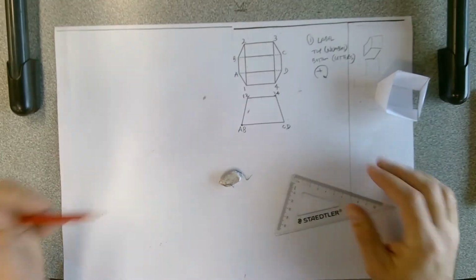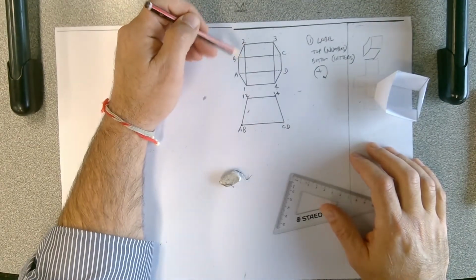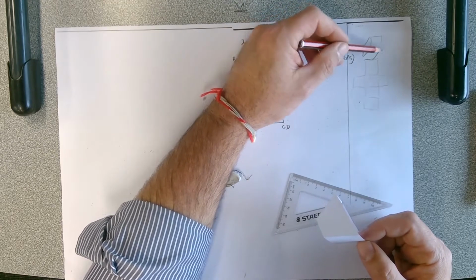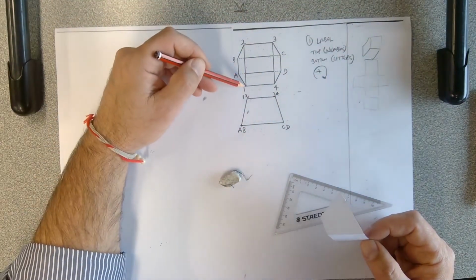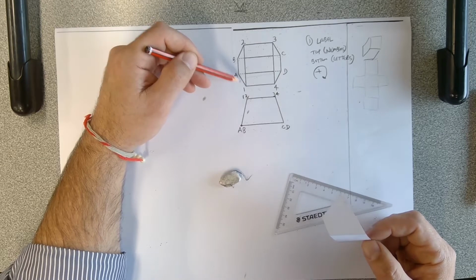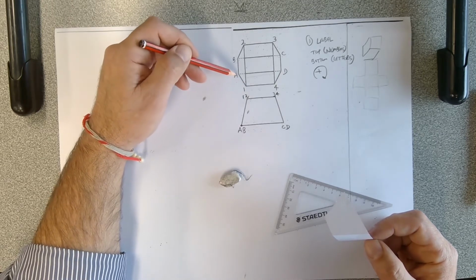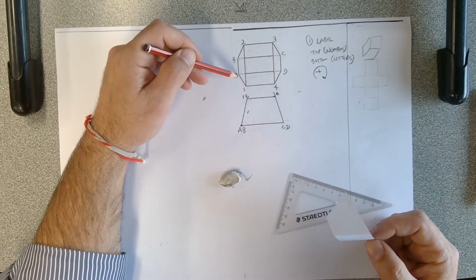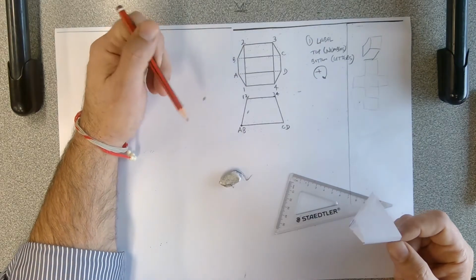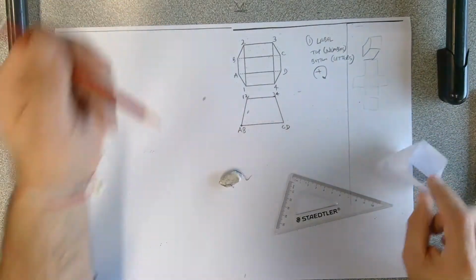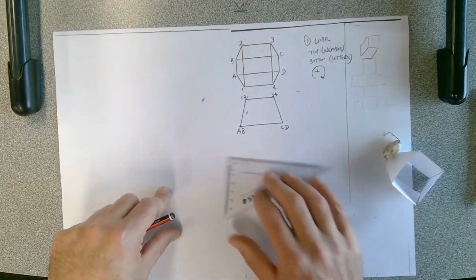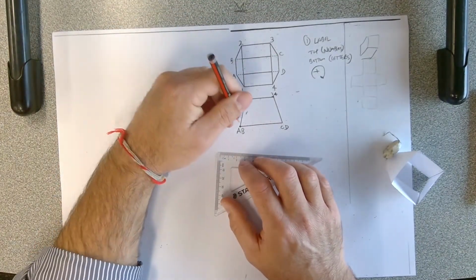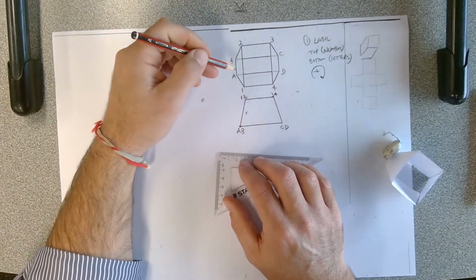Okay, but you've got lots of views that are lines that are not true length. So when you were dealing with a cube, it's pretty easy to tell that horizontals and verticals are true lengths. But this length here, say A1, it's going to be harder to ascertain the length of that particular line, because of the angles that are involved. Okay, so this is why we need to use triangulation. So we've labeled. We have to remember those rules about if it's point view in one view, it's a true length in the other.